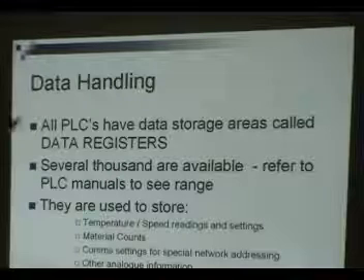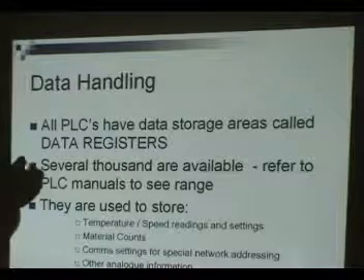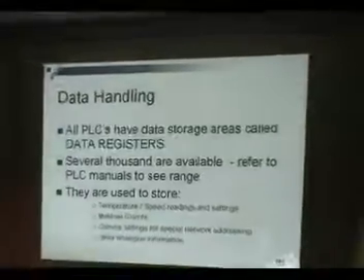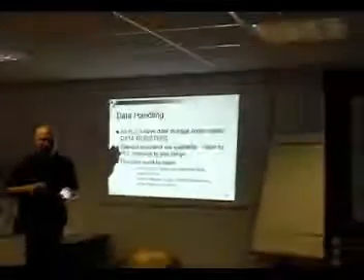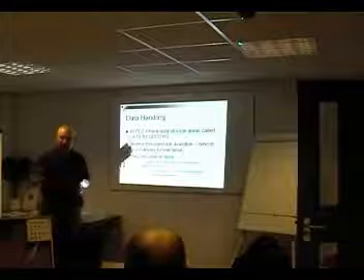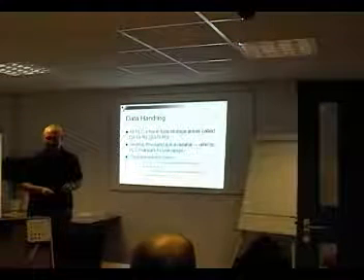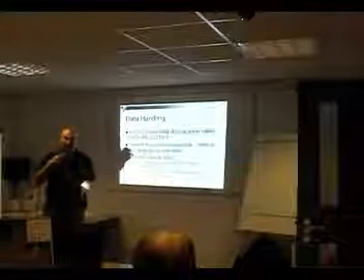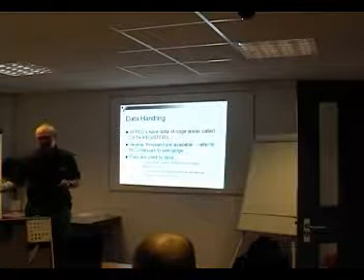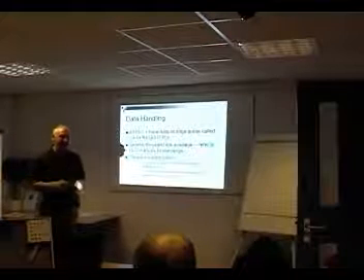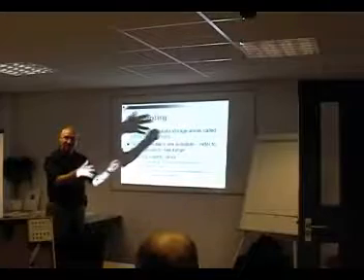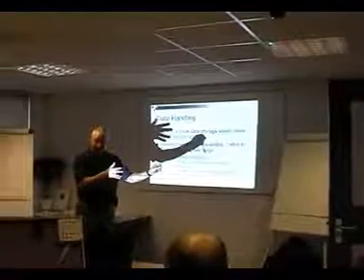It's funny that because some people say, well, what do you use counters for? To count material. No, you don't. You count events for the timer, not the number of materials. So if you have bottles going down a conveyor, you don't use a counter to count how many there are. The counter is there to count the number of events, and then once those events are completed, you then enable another one. So you might use a counter to count how many bottles are passing and then stop that process and enable something else. Yeah?